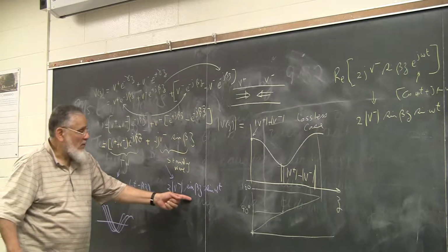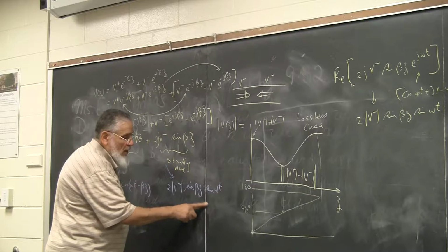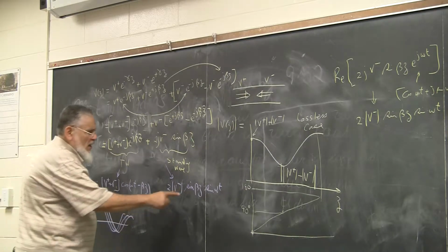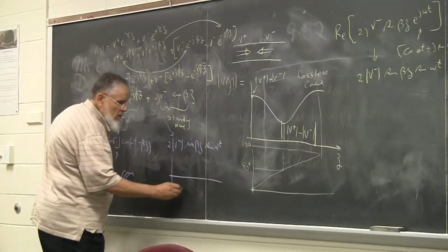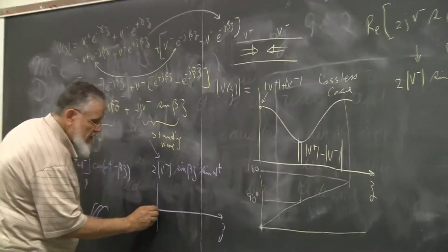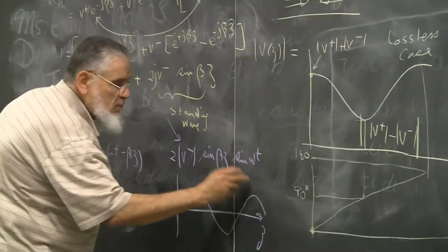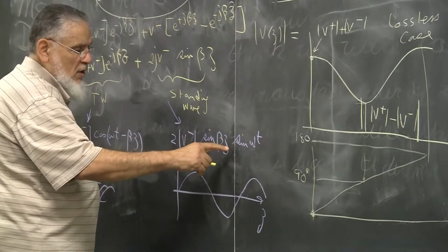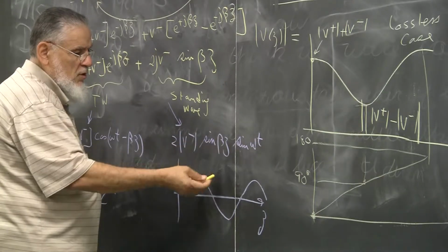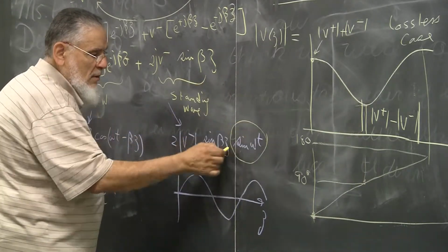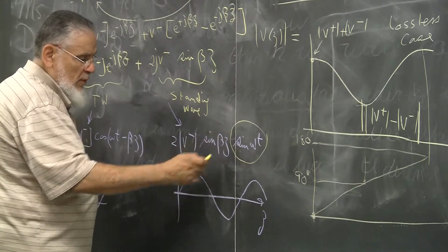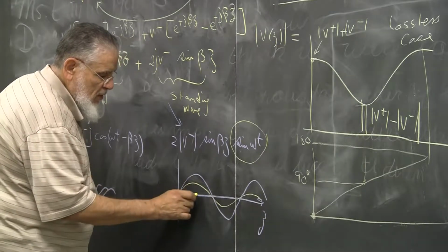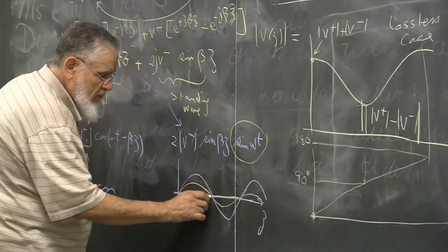The standing wave part now, let's try to map that, because we haven't seen that before. We've played this game here, but we didn't do this one. You have a sine beta z. So with z, it goes like a sine, but multiplied by sine omega t. And as t changes, that number here is going to change, but it's not going to change the waveform. It's going to change the amplitude, because that's really a multiplier of this. So as a multiplier, it will be a fraction. It could be a 0. It could go negative.